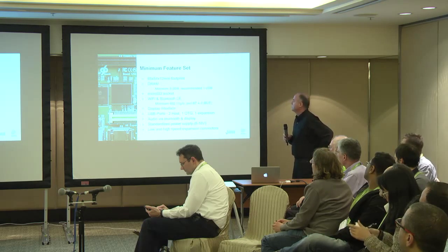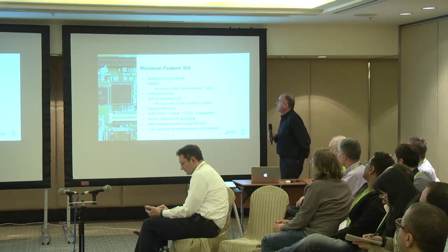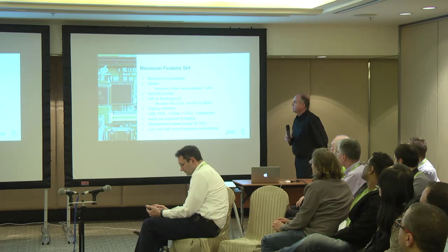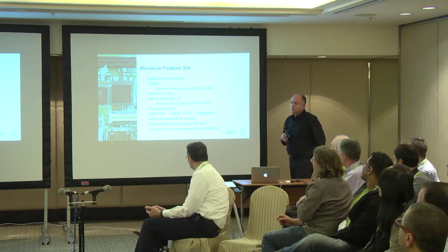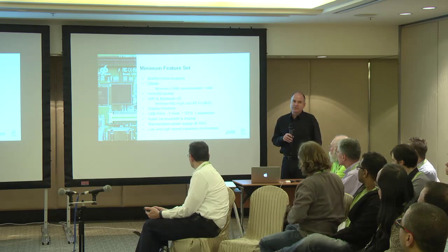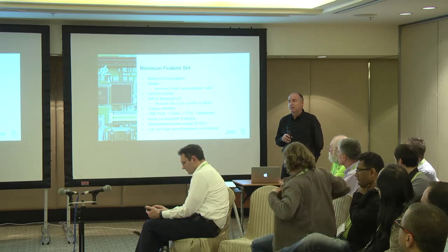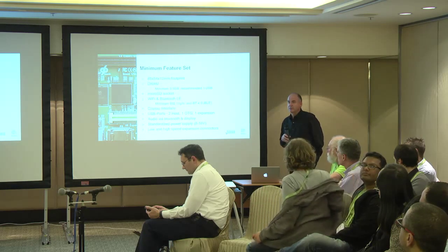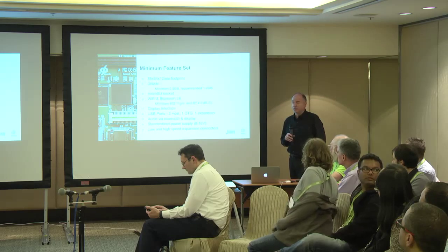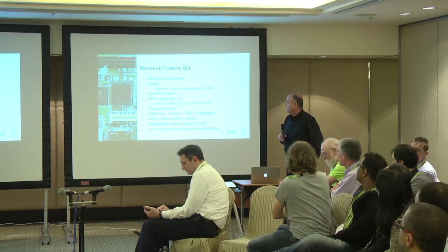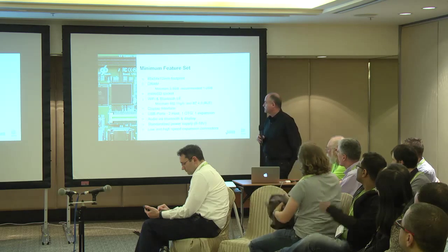So that's a difficult decision, and we'll come to it in a minute. Quick hardware summary. This is the minimum feature set for the consumer edition: 0.5 GB of DRAM. That's really more for the embedded guys. Once you start wanting Android, particularly on a 64-bit board, you've got to have at least 1 GB. There are companies who are building and designing boards with 2 GB. Wi-Fi, Bluetooth LE, just discussed. Display interface.